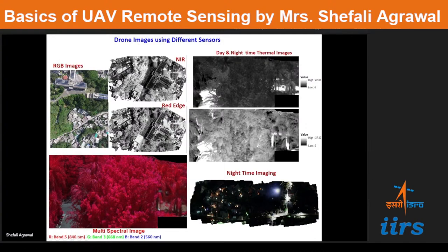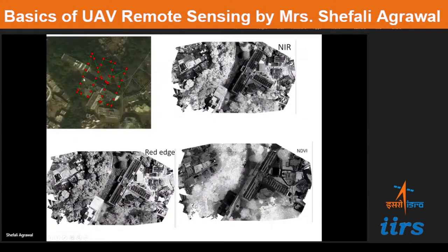So this is what I said. You have to define the mission, that is, the locations where it will click and collect the photographs depending on the overlap requirement. So these are the waypoints along which path it will collect. It will start from here. This is your takeoff site. It will go like this, collect like this, fly like this, collect data and land at this point. So all this needs to be defined in the mission planning software.